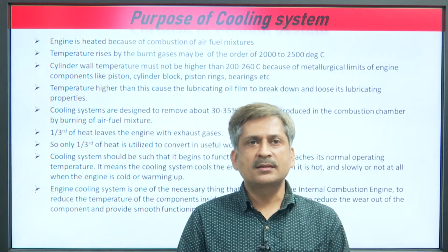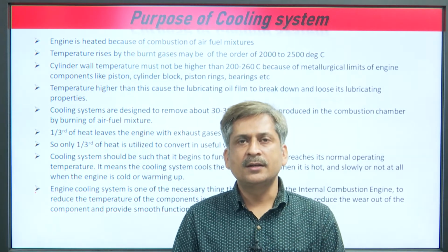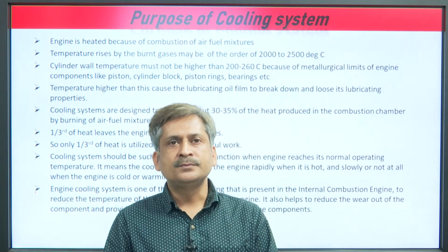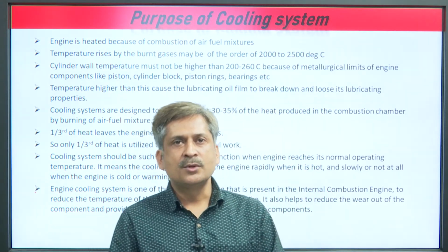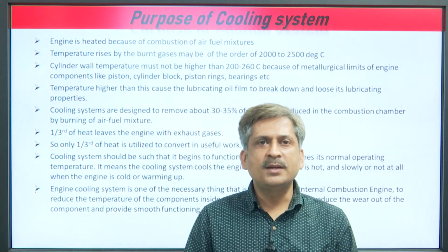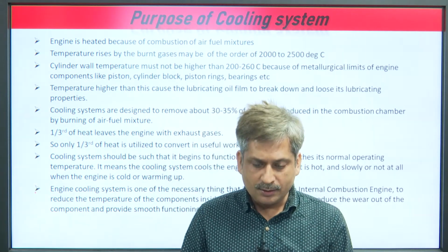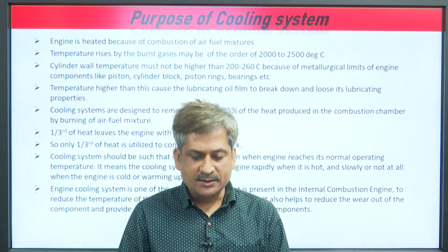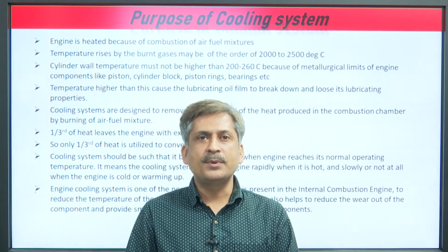I have discussed that approximately 1/3 of the heat has to be removed from the engine. So, the cooling system should be such that it begins to function when the engine reaches its operating temperature.